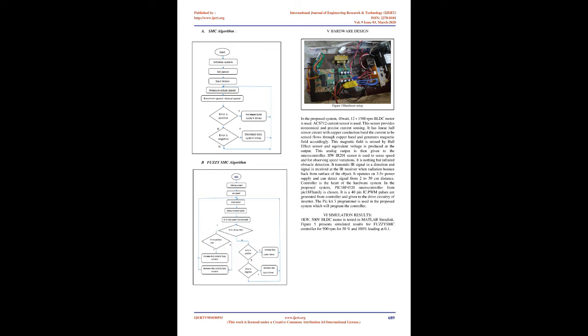In case of ideal sliding mode, the robustness property is maintained by control which brings the system close to S=0, but practically the system has limit cycle behavior and therefore chattering is always there. Chattering is high frequency oscillation which makes the system oscillate continuously. This is the biggest disadvantage of the sliding mode controller.